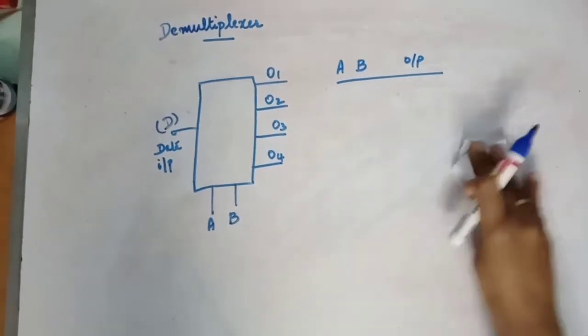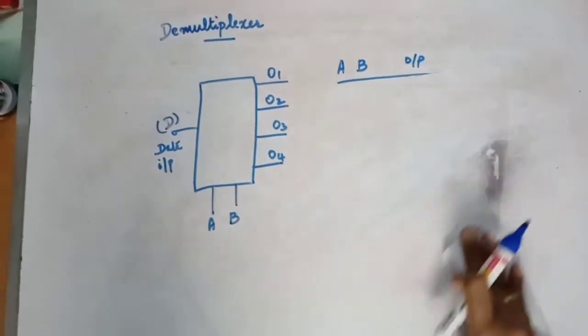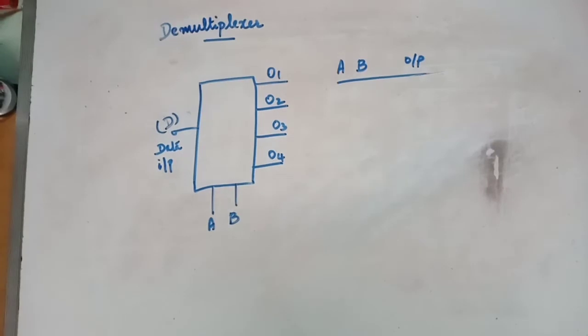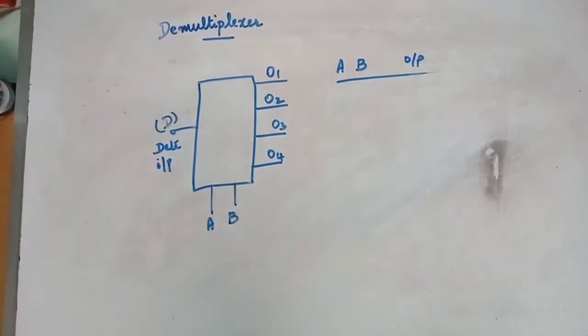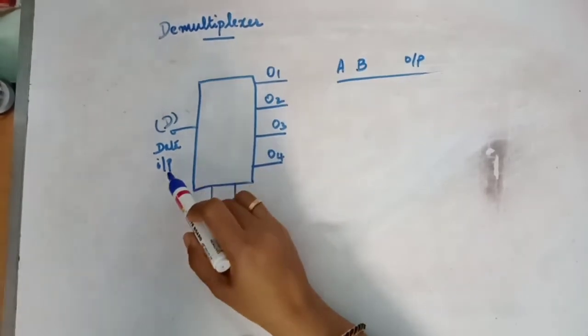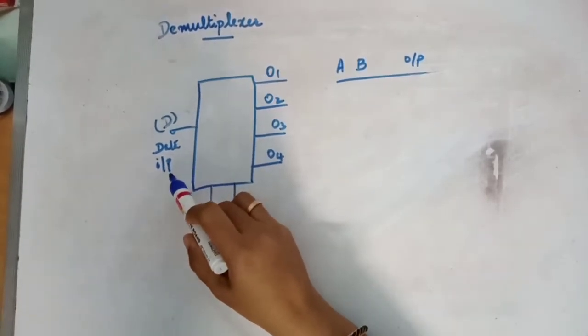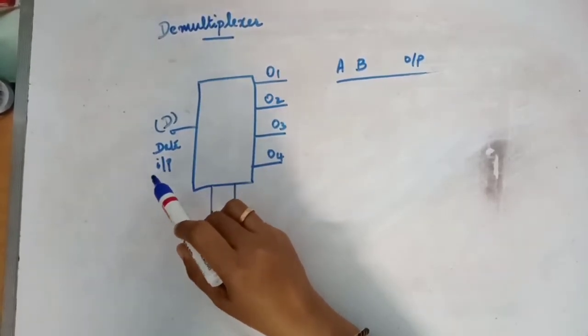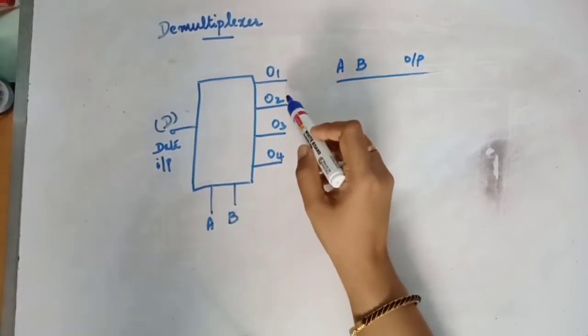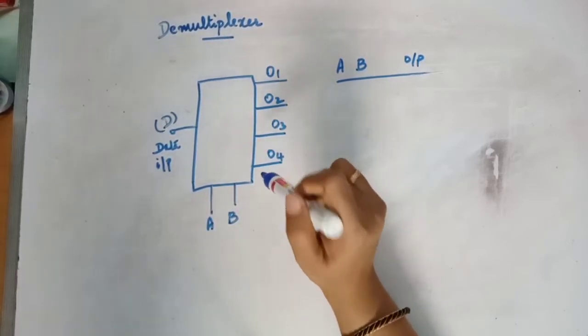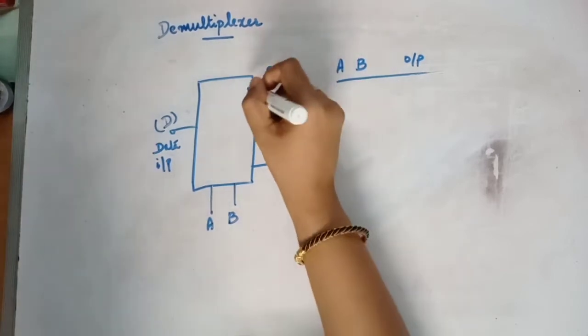That is the difference between a multiplexer and a demultiplexer. In the case of a multiplexer, one of the input lines is selected, and whatever is in that input line will go to the single output line. In the case of demux, the single input will be transferred to one of the output lines selected.